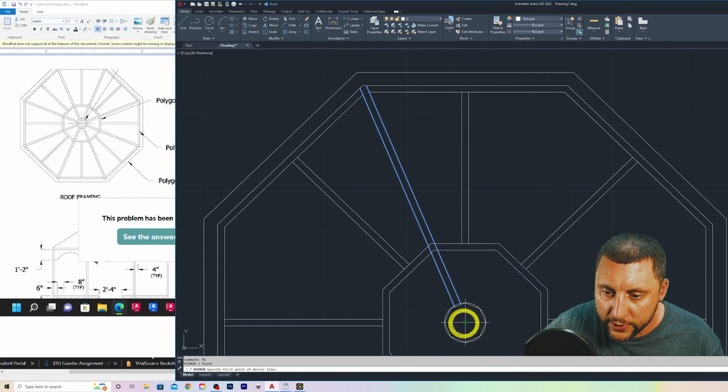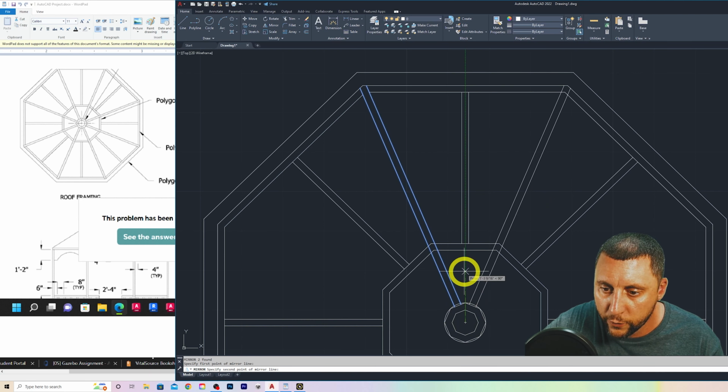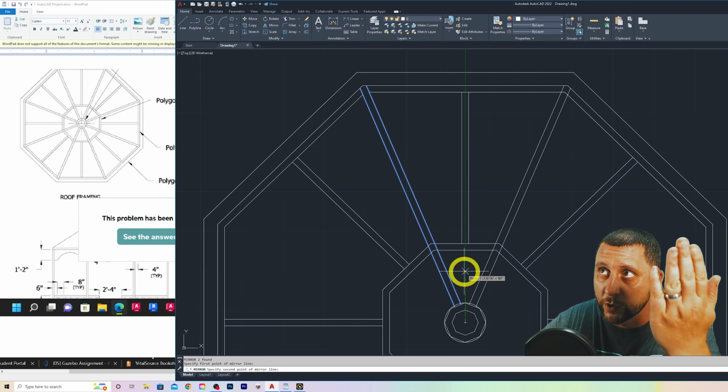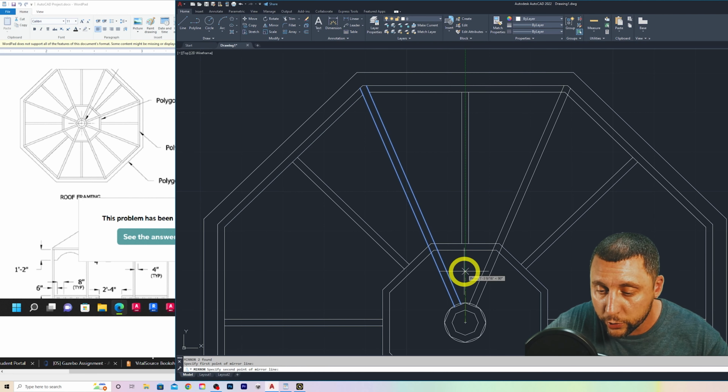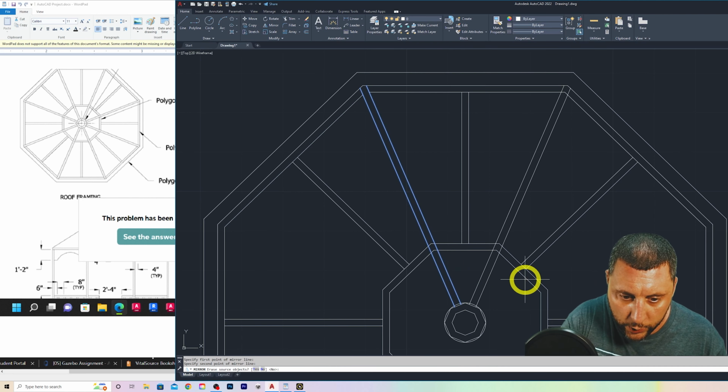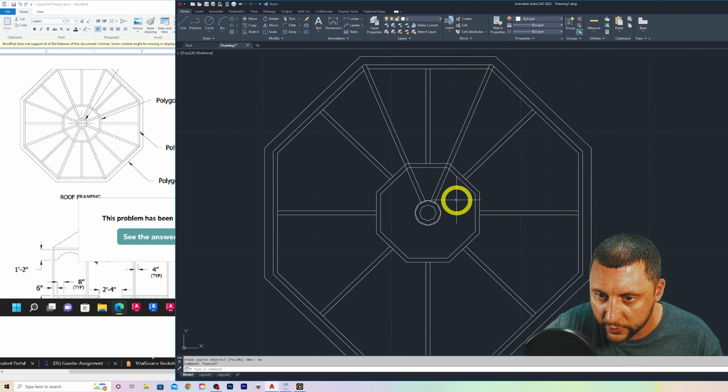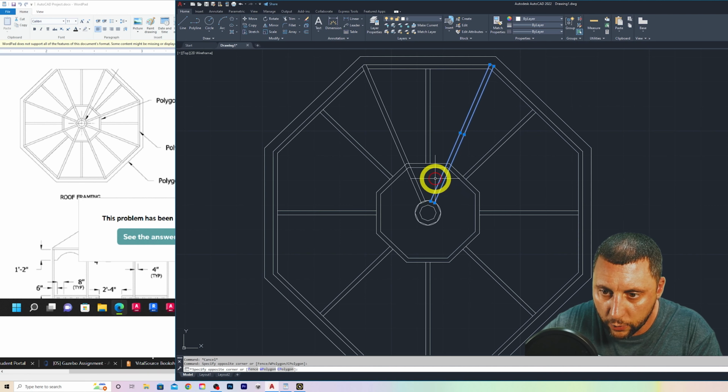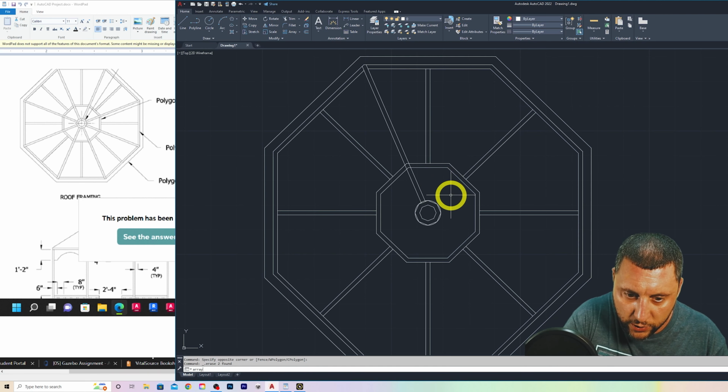You're going to go off of the center point, and you're going to go straight up, and it's going to mirror it over that line that you're creating from one side to the other, a vertical mirror. And then it would say, do you want to erase the source? You would say no, and then you're left with 2 of them like this, okay? But I'm going to do array instead. Again, it's a lot faster, so here we go.